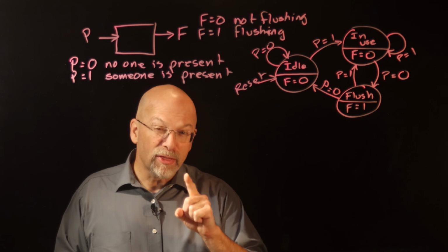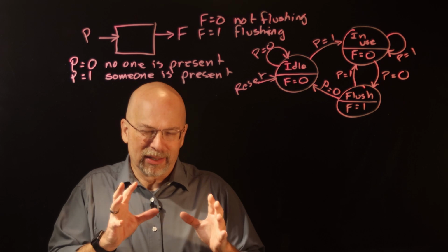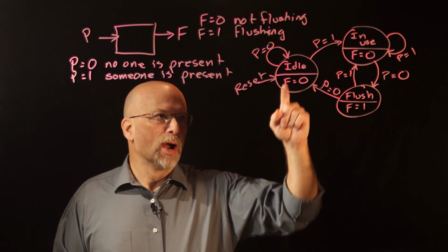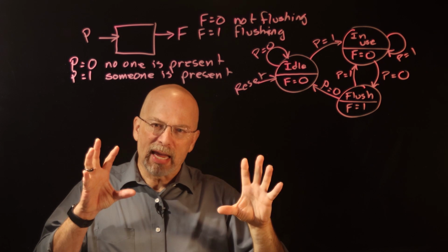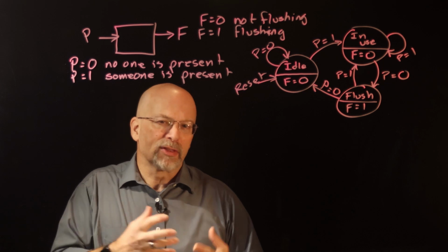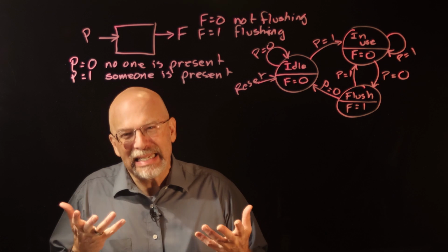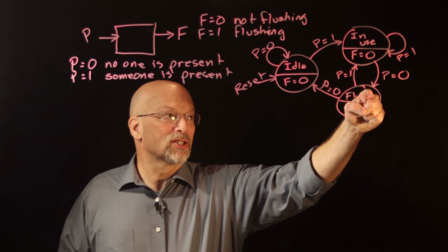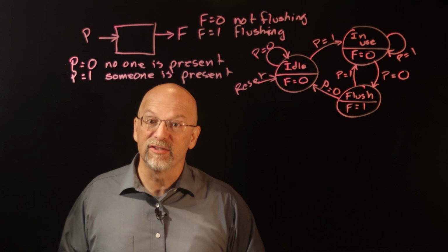Now, there's another possible way that an error could occur. It's really hard to create this error if you're developing the state diagram the way we've been developing them, where we simply create states as we need them. But if you've got a bunch of states and you start connecting them with transitions, it's possible that you've created a state that there's no way to get to. In general, the easiest way to identify a state that's impossible to get to is that it doesn't have any transitions coming into it. It has an in count, the term used from graph theory, of 0.